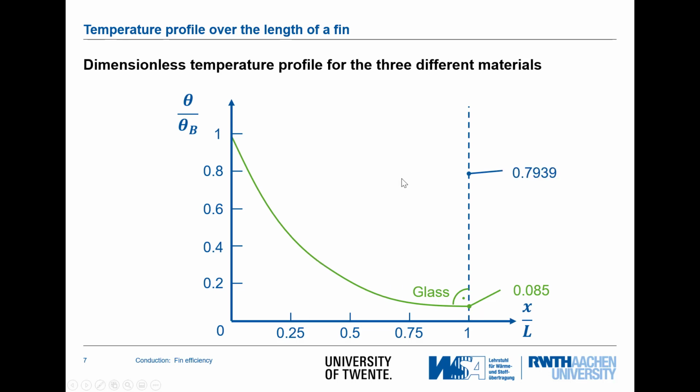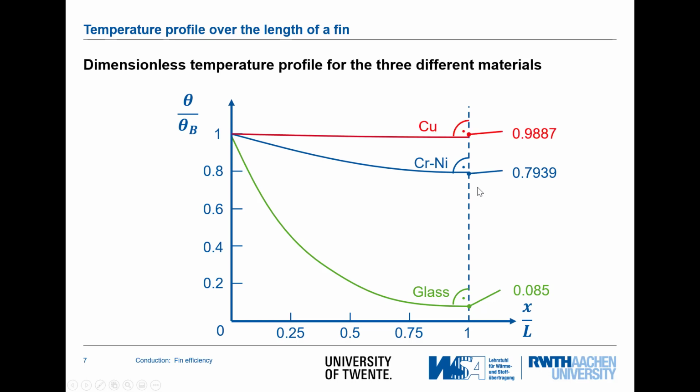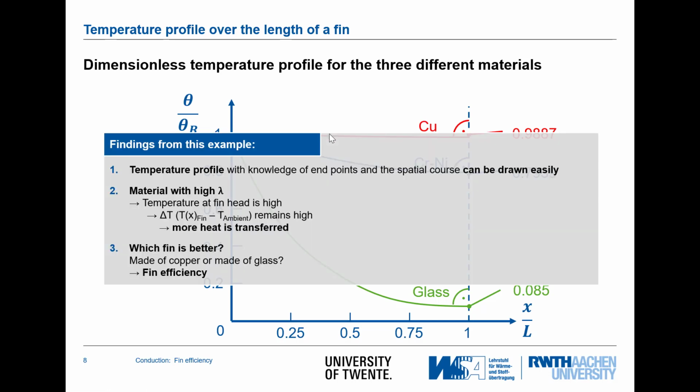Now for the other material, for the chrome nickel steel, we can draw the profile in a similar manner, and also for the copper. Remember here the temperature of the copper material is nearly homogeneous inside the fin.